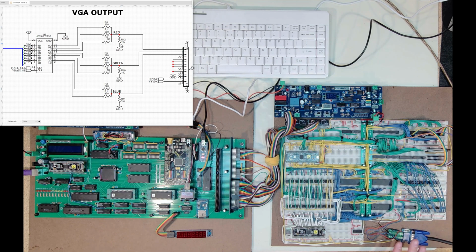So that is where I'm at, and then I've done some initial coding just to do a really simple test here. What I want to be able to do is output not just an uninitialized output of RAM to my monitor, which would show up as kind of a snowy, white noise type effect because it's random data in that. I wanted to initialize that to all zeros, in other words, just write a black screen. And I also wanted to see if I could write an all white screen just to make sure that I can fill in the screen.